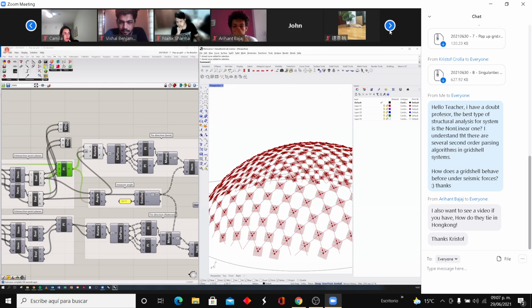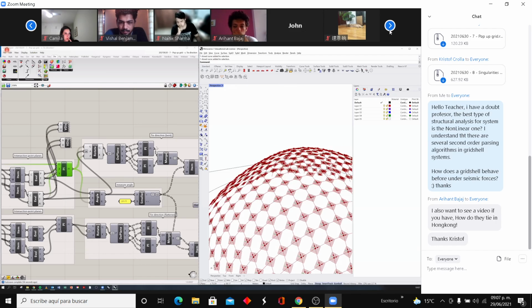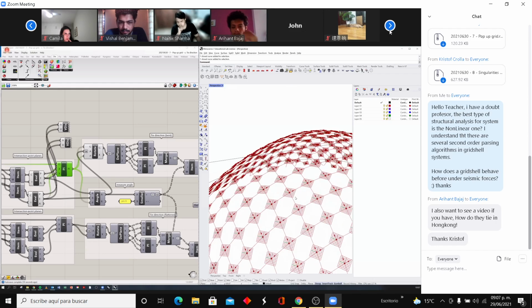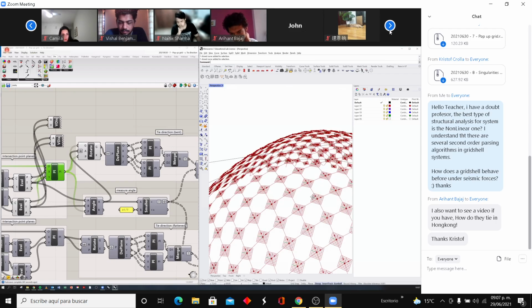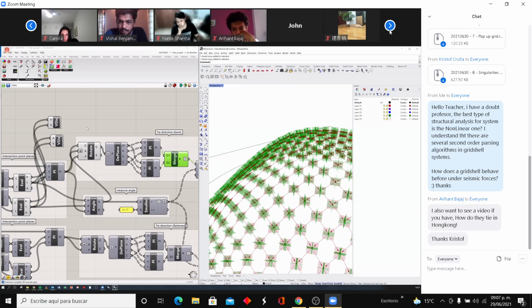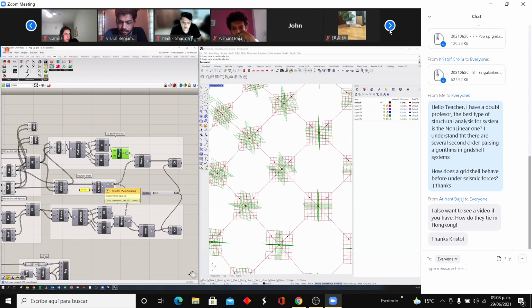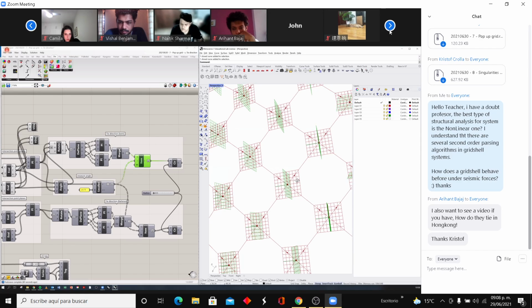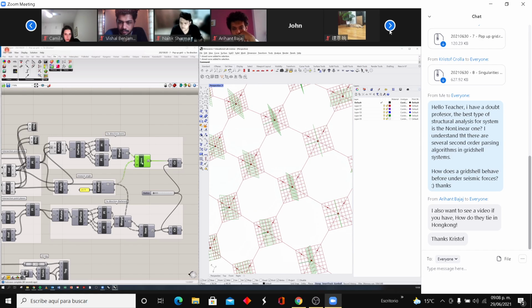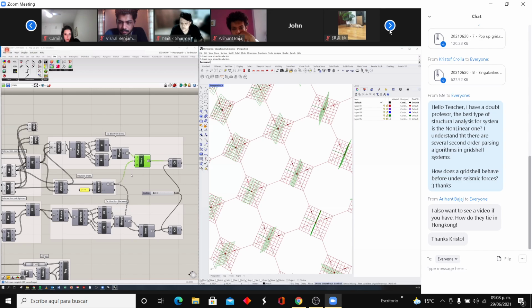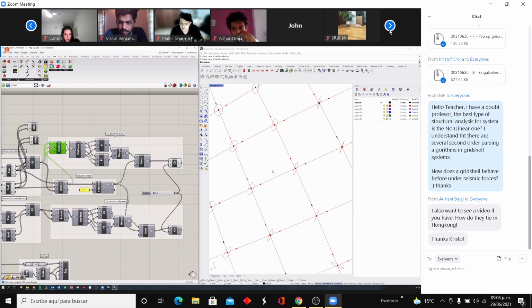I'm going to deconstruct it in X, Y, Z directions, and I'm going to recreate these planes on top of it, just using my X, Y, Z values. So what I have now is a perpendicular plane based on my bisector. Depending on whether I'm smaller or larger than this one, I can select my 0 item or my first item very straightforwardly, and I basically arrive at my final plane here. And then I can put a circle on it. So that's that, very straightforward actually.